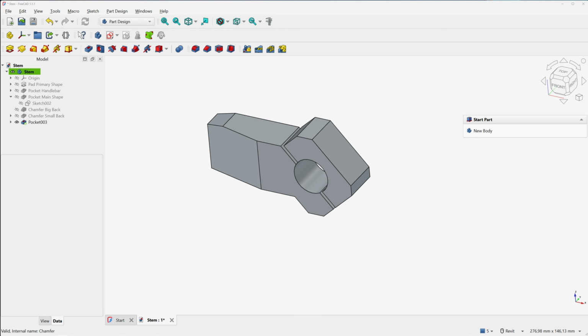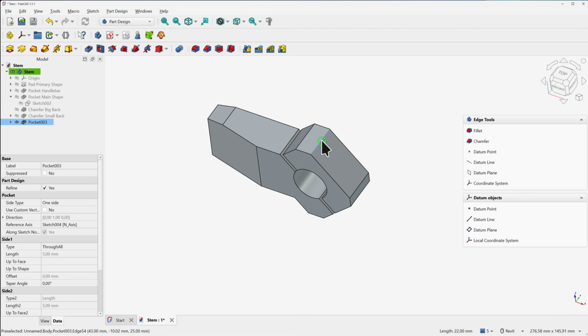To achieve this, we're going to perform a small push surface operation. We want this front part to have a thickness of 16 mm. If you can't remember the original thickness, you can simply select an edge across the width, and the distance will appear in the bottom right corner. Here we can see it's 22 mm, which means we need to subtract 6 mm.